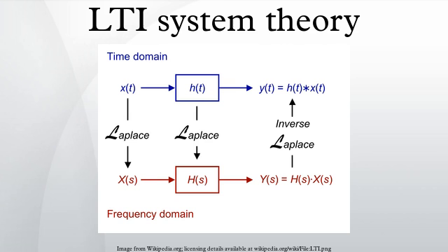The Laplace transform is usually used in the context of one-sided signals, that is, signals that are zero for all values of t less than some value. Usually, this start time is set to 0, for convenience and without loss of generality, with the transform integral being taken from 0 to infinity. The Fourier transform is used for analyzing systems that process signals that are infinite in extent, such as modulated sinusoids, even though it cannot be directly applied to input and output signals that are not square integrable. The Laplace transform actually works directly for these signals if they are zero before a start time, even if they are not square integrable, for stable systems.